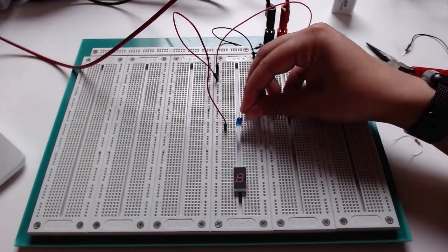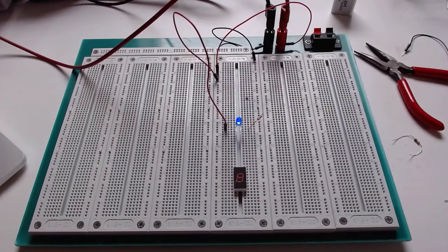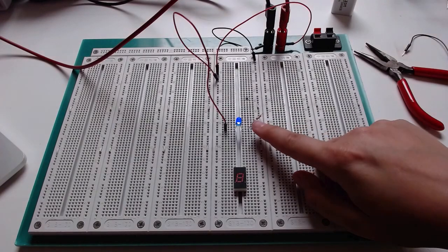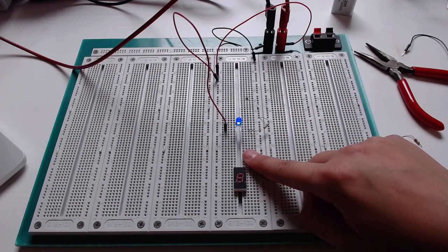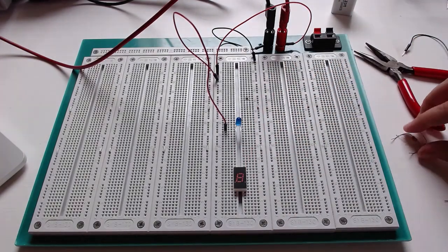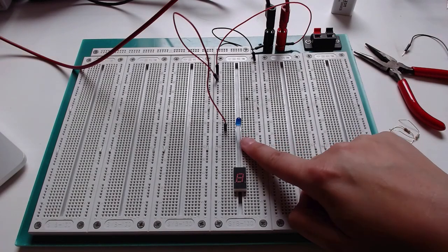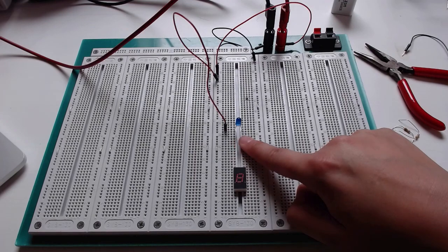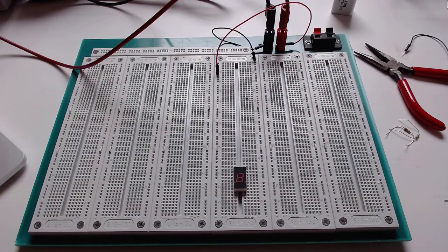So this is a 10K resistor, and at a certain point, the LED just becomes really, really dim, to the point where if I have a really, really high resistor in here, the LED is basically going to be off. Okay, so again, the most important metric is what is the smallest resistor value that I can get away with? And then from there, as long as it's larger than that, pick a resistor value that is comfortable for you to look at the LED without hurting your eyes. Okay, so that's just a single LED.